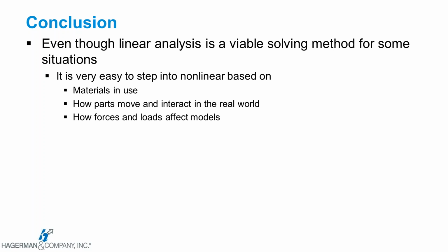How are the forces being applied to this component? Is it coming in contact with other models? What types of materials am I using, and do they have low yield points that I'm probably going to start stepping into? And then lastly, how do the forces on my component apply to this model? Is it a pressure load? Is it a force that's going to change over time? And those sort of things we can effectively solve for in a nonlinear analysis. And remember, nature is nonlinear.